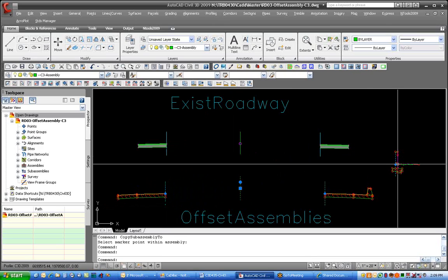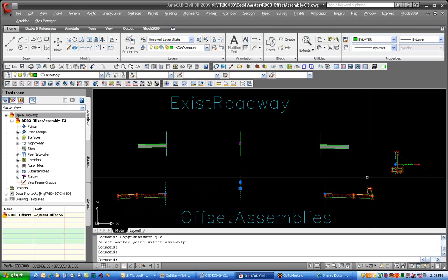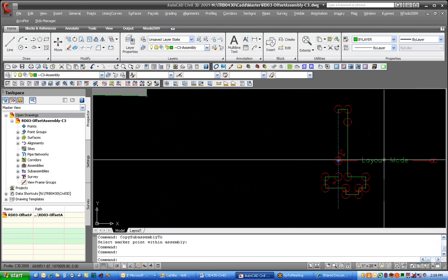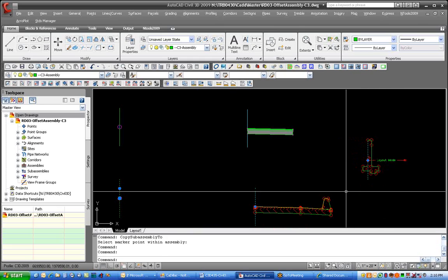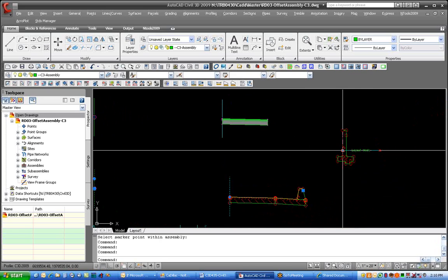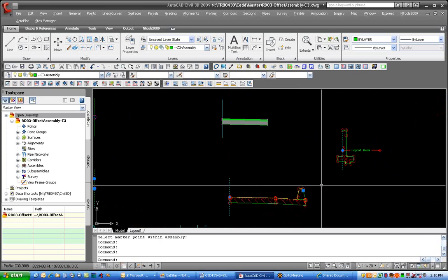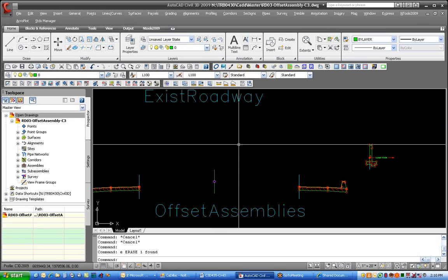Same thing for the retaining walls here, or for these objects out here. And then we did what's called a link to marked point, where we can say take this line and draw it back to, and I get a little mark point right there, and it'll draw it from here to here in the cross section as it processes each section. So hopefully that isn't too vague. Let me get rid of this. I just wanted to give you a quick heads up on how this was built.